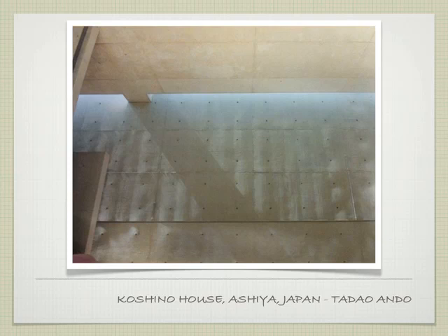When you're putting these two pieces together, you're going to put the verticals that run all the way through, so your studs aren't just across one piece. They're going to run further. When that happens, it helps to tie them all together. So it's just stacked. There's no tongue and groove. There's nothing fancy about it, which is why you can see where the joint is.